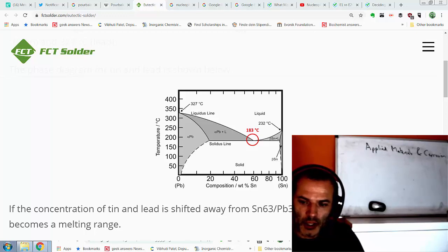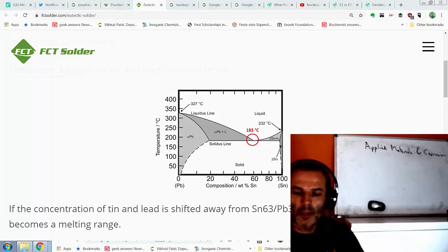So here we've got lead with a little bit of tin in it up to this point, so we can get about 18% of tin in our solid lead before it separates, and we get a stronger concentration of tin in the liquid and a higher concentration of lead in the solid. This is a thermodynamic diagram, so effectively if we go here and we have a solid, it is implying that we wait for infinite time.